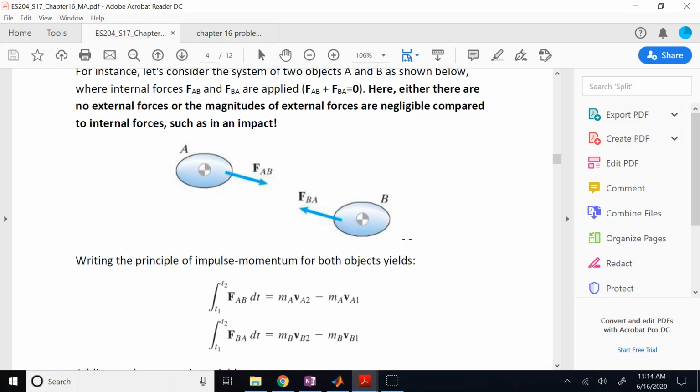Well, should we neglect it? We know they exist, but why do we neglect them? Sometimes these masses are not really small and the gravity forces are not small. Should we neglect them? Well, it depends on the application, but mostly we can because of two things. First of all, in most impacts, the magnitude of the impact force is significantly bigger than gravity. It is typically significantly bigger.